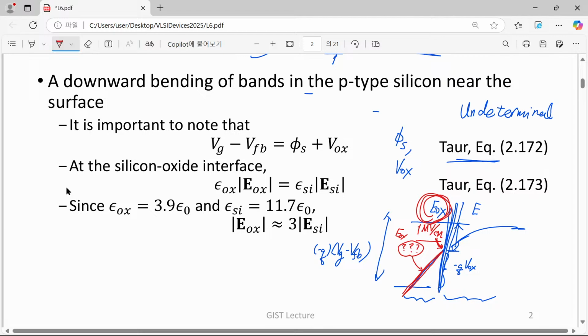Only one representation is enough. However, think about the semiconductor region. Can you say one single electric field fits all over your system? Unfortunately, it does not. For example, if we go too deep into the substrate, then obviously your electric field becomes 0.